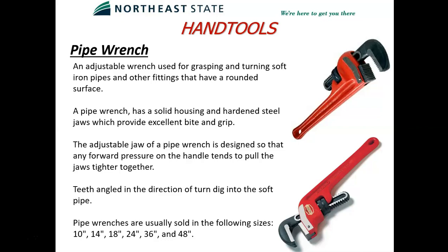But the moving jaw will kind of flex. It has a little bit of flex in it, it's got movement in it, I should say. So when you tighten it down, that movement along with those reverse serrated edges, they clamp onto that pipe really tight. And they'll actually bite into the metal and leave serrated marks in the metal if you turn hard enough.